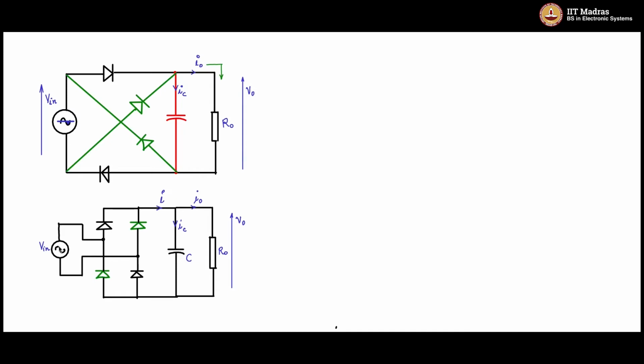So this is how the full bridge rectifier operates, and here both the positive part and the negative part are utilized. Therefore you will see the ripple is lesser, or for a given ripple the capacitance size will be smaller. So let us also look at the waveforms. The capacitance value will change, with a very minor change in the diode ratings.